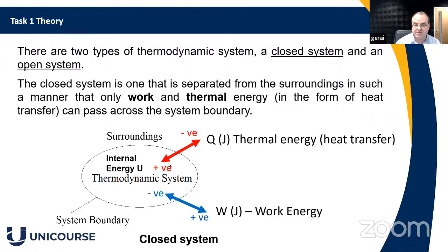and into the system, thermal energy is going to be positive. Now, for now, we're going to look at work transferred across the boundary. So it'd be a piston moving, for instance, and the system expands and the piston drives something. So then the only energy transferred across that boundary in a closed system is going to be out of the system. The sign convention is positive, and into the system, it's going to be negative.